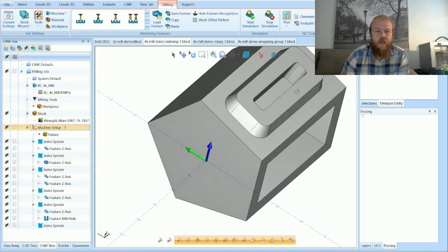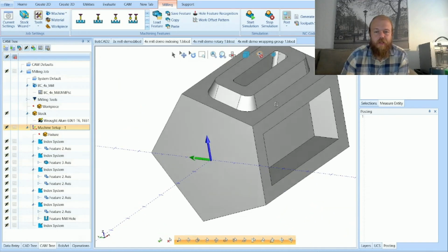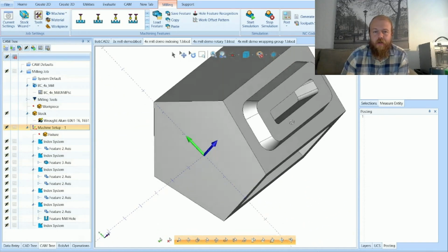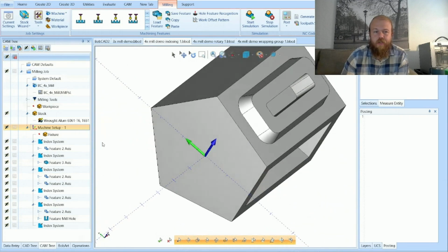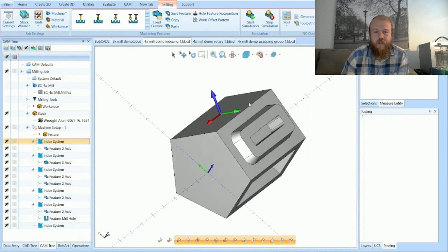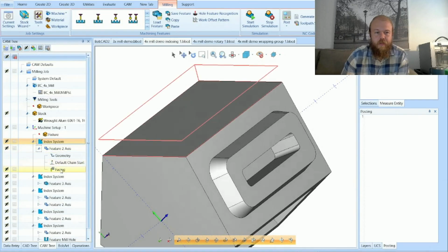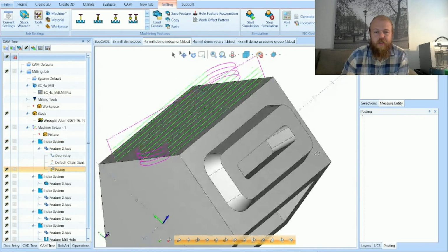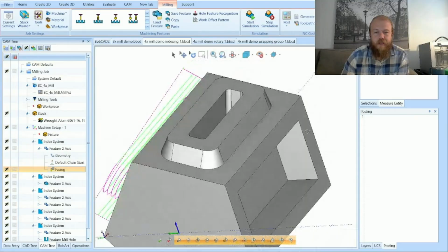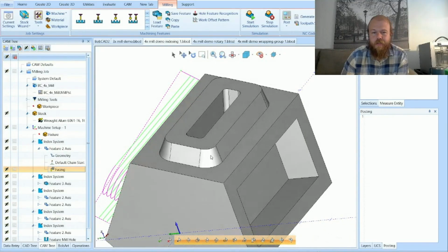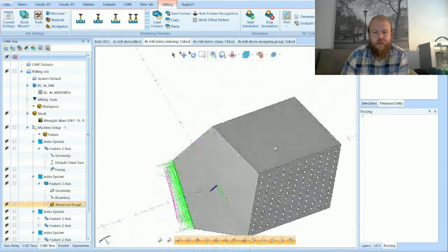And we're going to have the stock rotate around our rotary table in the A-axis so that it's to this location, and we can do a facing operation on this side. Then it'll rotate around in the A-axis and lock at that location, and do a 3-axis milling operation on this side and keep rotating around from there.